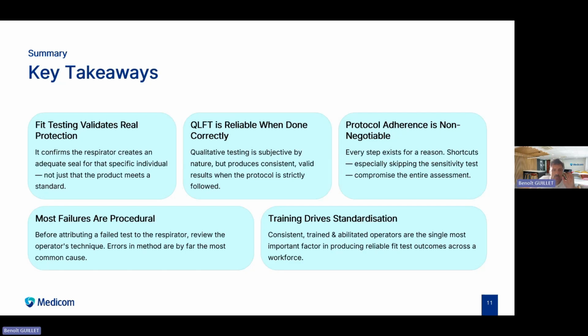Most of the failures, as I mentioned just before, are procedural. Many of the time, they are errors in the method. So you need to take time to follow all the procedures of the fit testing and all the different exercises, and to check beforehand, as I mentioned, that the wearer can really smell or taste the agent.